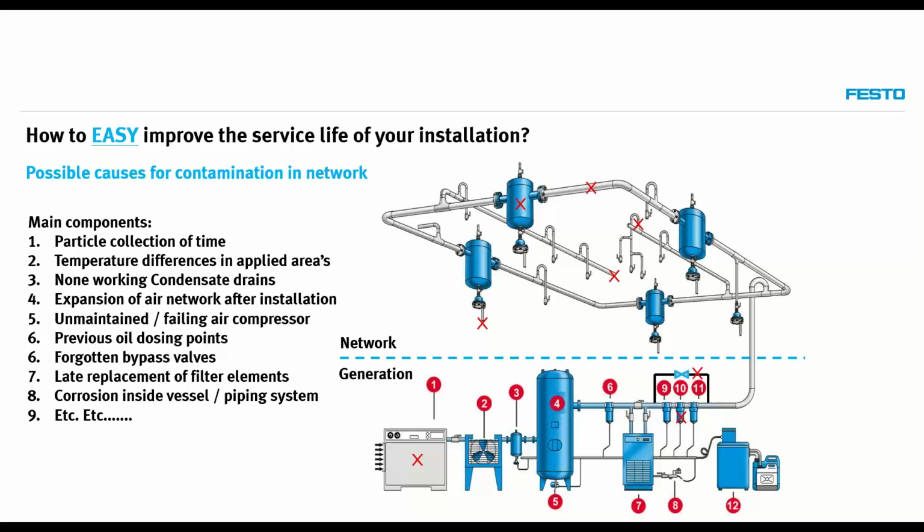You need to keep maintaining it, and the efforts are going to be higher. So good compressed air quality has a very good impact and can affect the amount of maintenance needed. Sometimes we see bypass valves for filters to replace them, and people forget to close them at the end of the servicing of the filter units. So over a period of time, much air enters the system without any type of filtration.